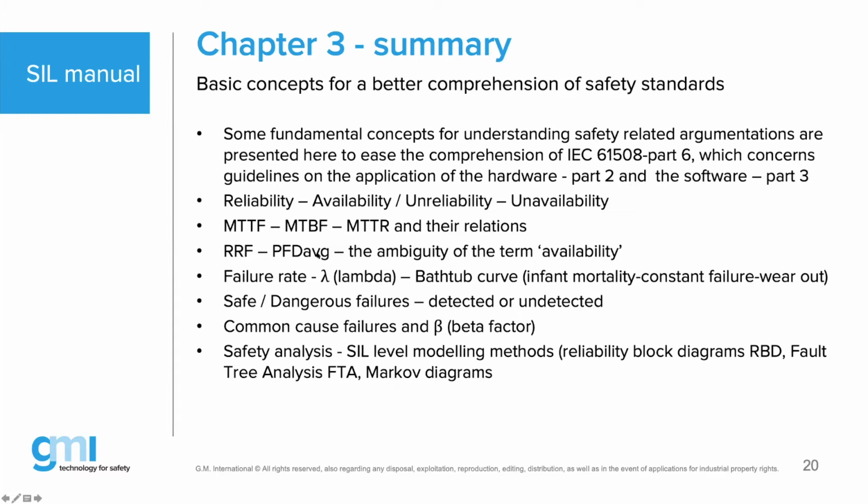Because that is a bit of the struggle in the industry today, that many people use numbers, not knowing where the numbers come from, and they start to believe or even trust them. That's, of course, not really a good approach in safety, to assume that the number will be correct. Failure rates, that's the famous lambda, the bathtub curve. You may have heard about the bathtub curve. When you start up, you have your infant mortality, then you have the constant failure rate, and you always go to a certain wear out where your equipment will stop working. Common causes are explained in there.